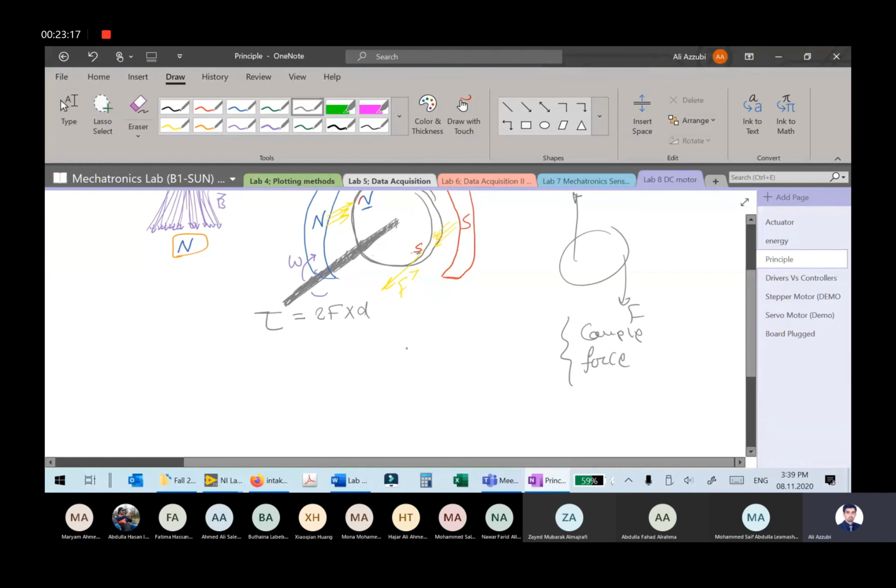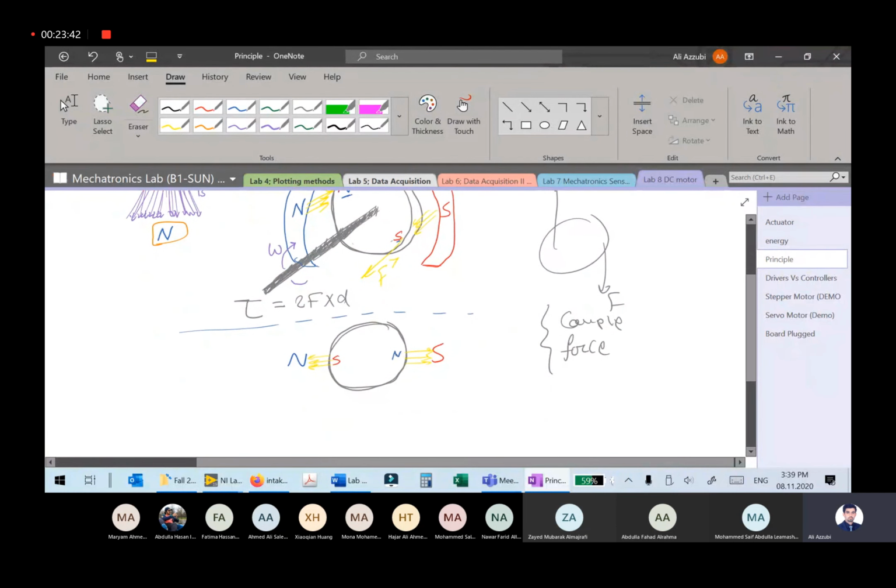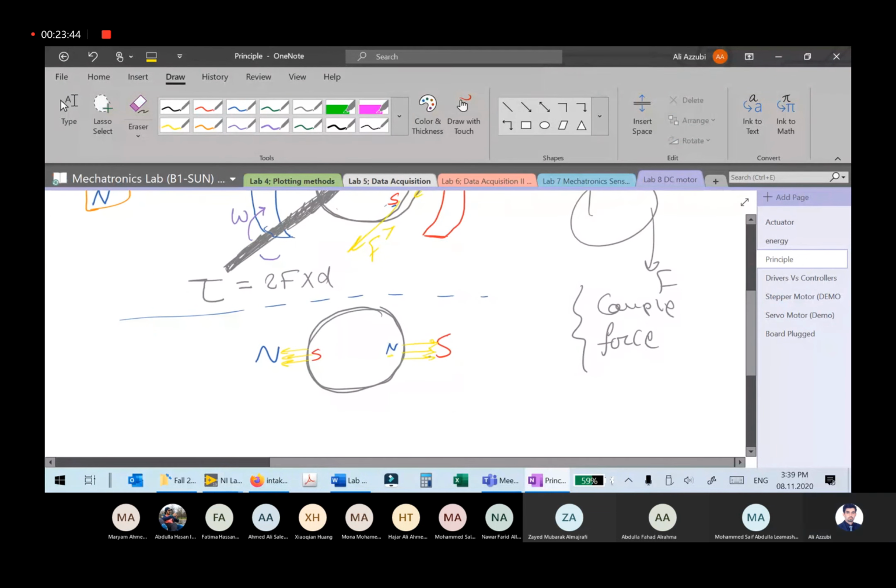When we have this rotor like this, so now I'll drop these magnets south and north. Okay, this critical condition is when you have the north here and the south here. Now what's going to happen? Instead of repelling, you'll have some attraction between them. Now at this location, the north is actually attracted to the south.